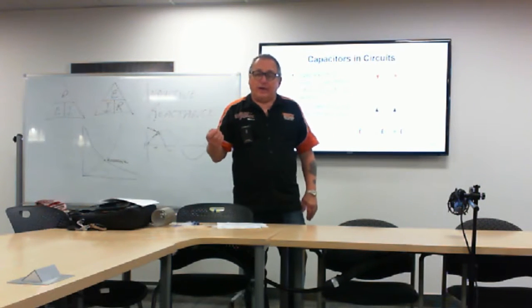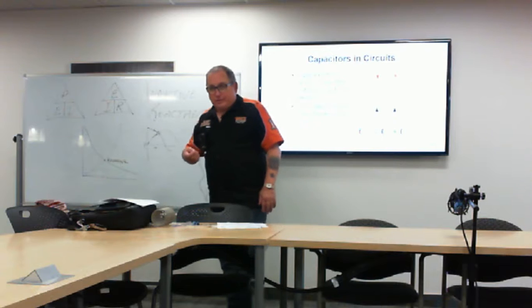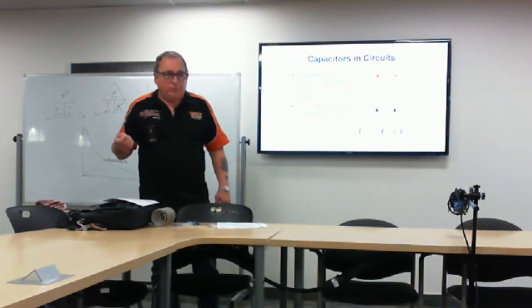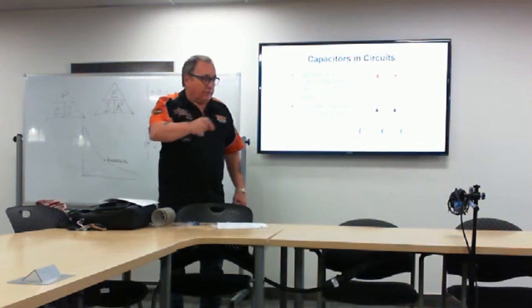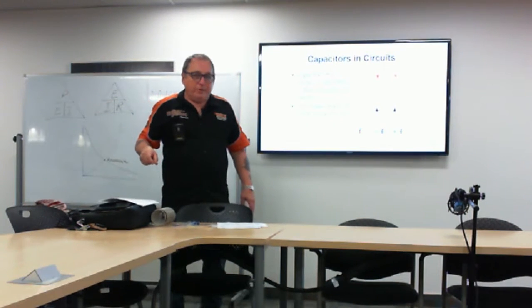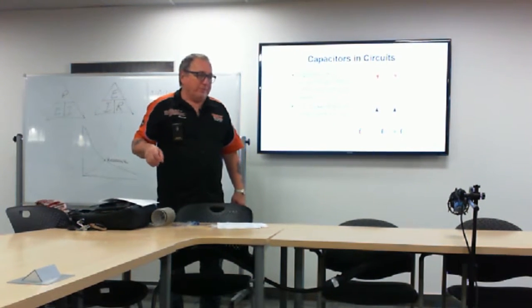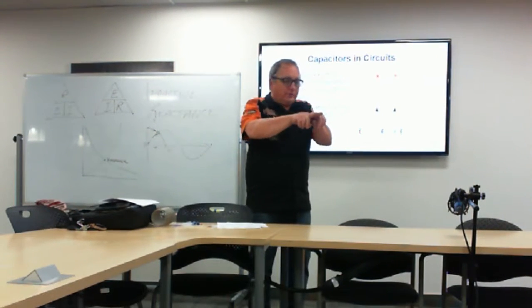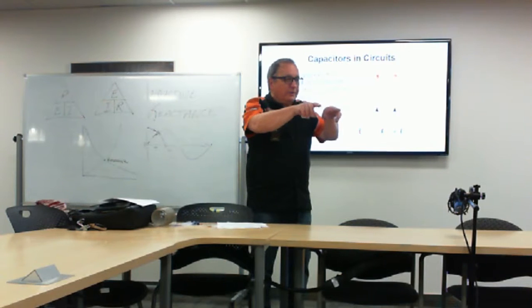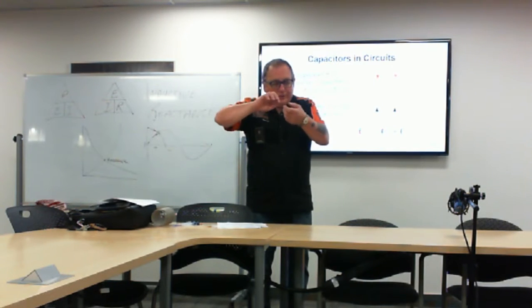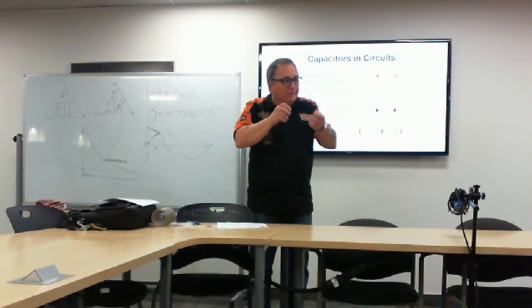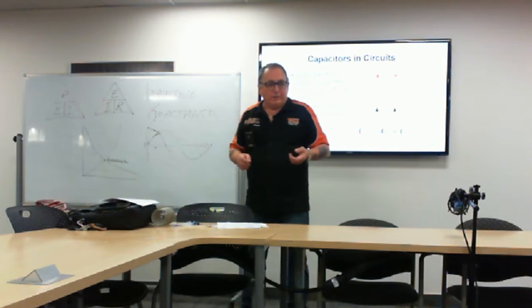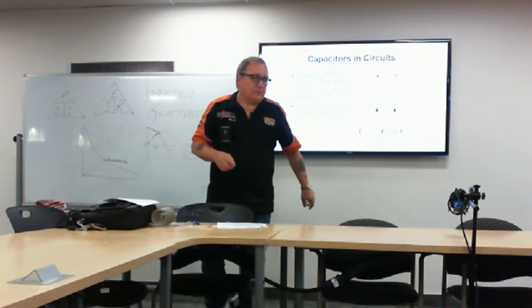For matching our antennas. And the best example of an impedance match is now out of date. But at one point we used to use twin lead into our television sets, and the rabbit ears and stuff. But you guys probably don't even remember that. And you used to get this little thing about this long, and it had the 2 leads coming out that went to the antenna, and then you screwed the coaxial cable into it. That's called a balun, a balanced, unbalanced device.